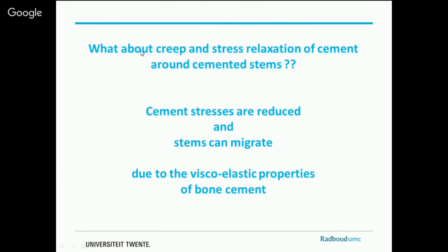Cement is a viscoelastic material. It's like plexiglass. And especially at 37 degrees and in a watery environment, it creeps. So what about creep and stress relaxation of this cement around these cemented stems? We expect that cement stresses are reduced because there is stress relaxation. But if there is stress relaxation, the implant can migrate. So that's what we expect.